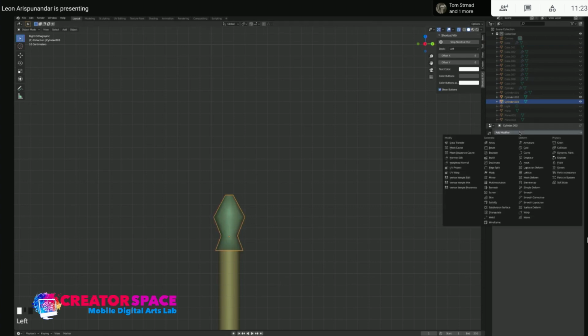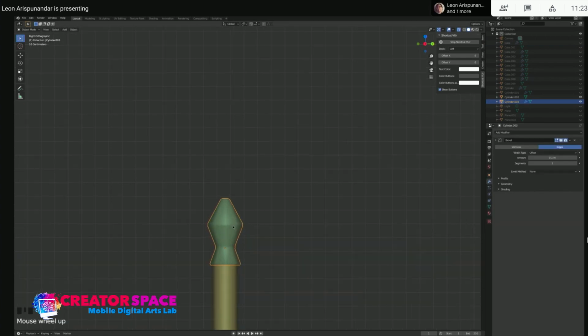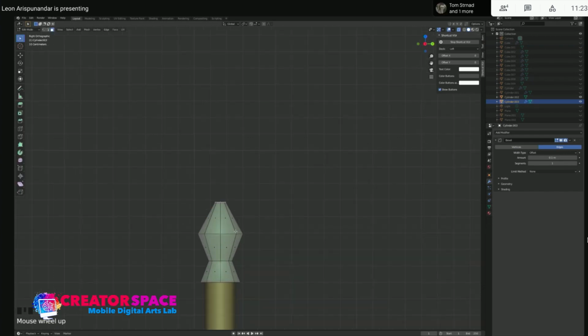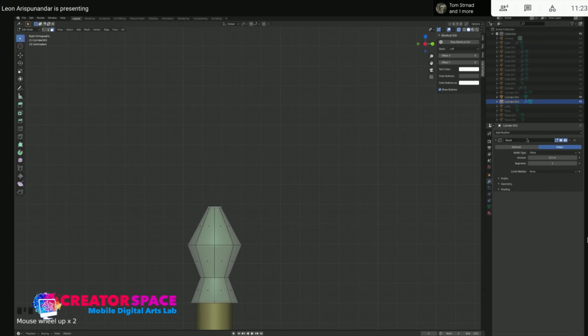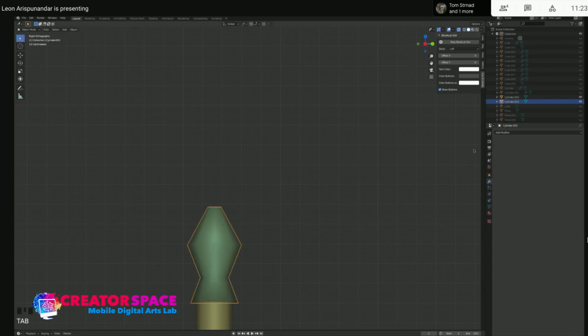Now, you probably think why we don't use a bevel. You can use a bevel, but I like the Subdivision Surface because you have more control, manually, compared to a bevel. With the bevel you have to play around with this number here, and I'm more visual, so I tend to like things where I can see if I need to add something.